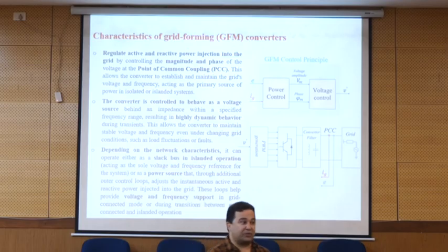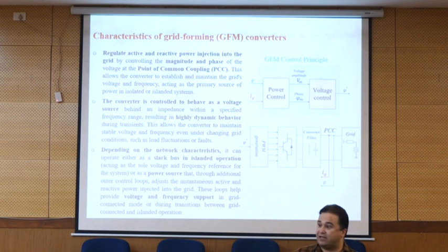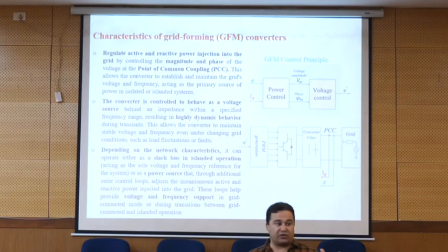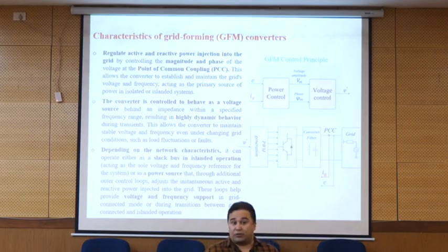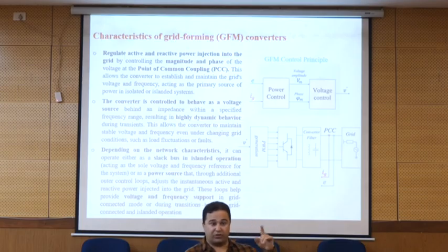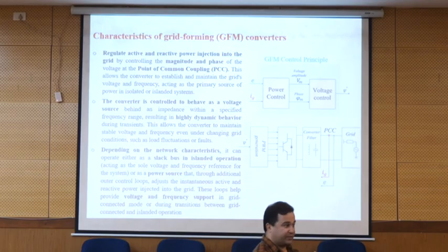So it means that your power should have high quality. And if it is 6%, it means that it is not in the standard that we need. So for this case, you can generate it, you can use it, but you cannot inject it to our grid, because our grid standard is less than 5%. Okay, so this is something that you need to follow.